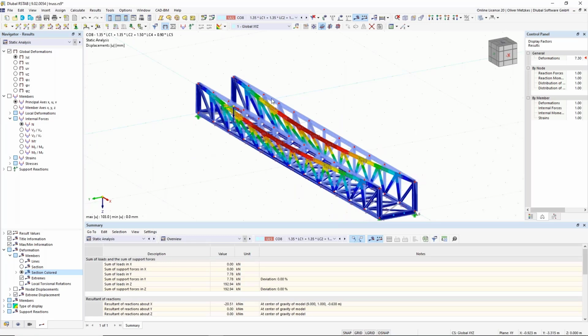So we have said, okay, we have no lateral restraint here. We have assumed all those vertical and diagonal members with hinges at the ends. So basically, I don't have any restraints in the middle. So it would be this one wave buckling shape for these members.